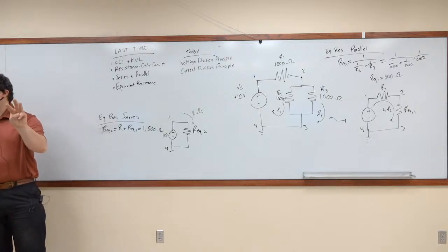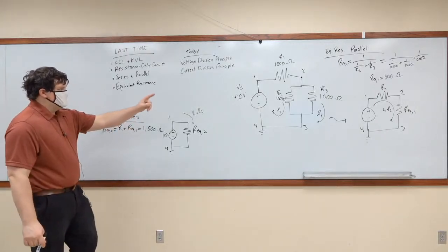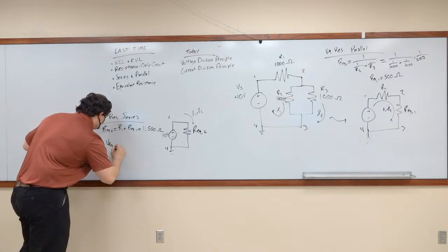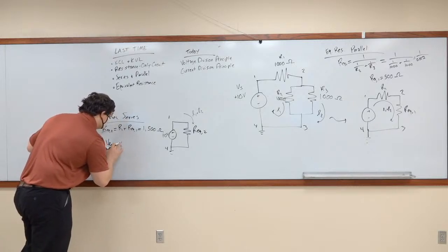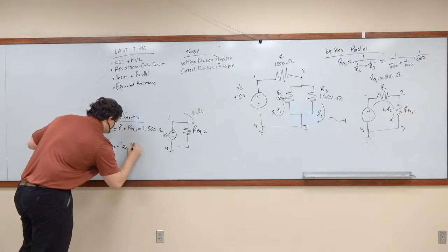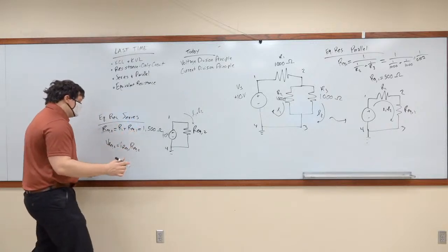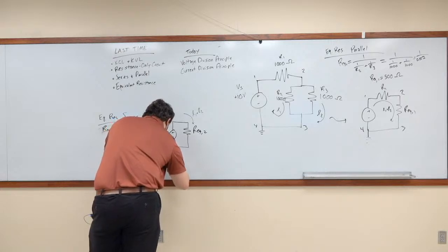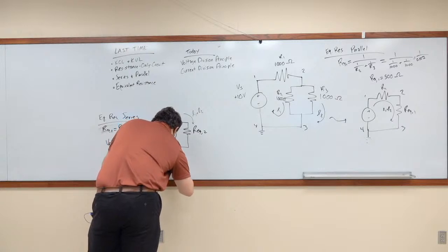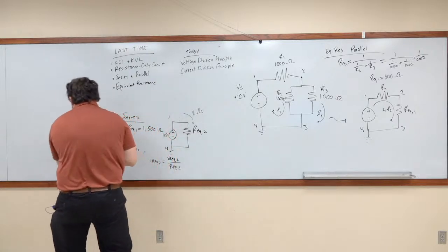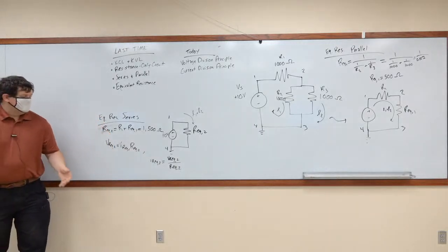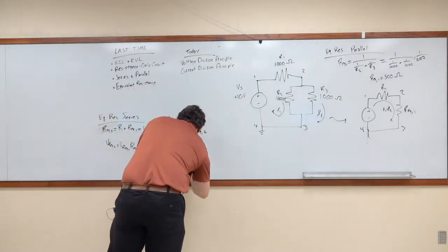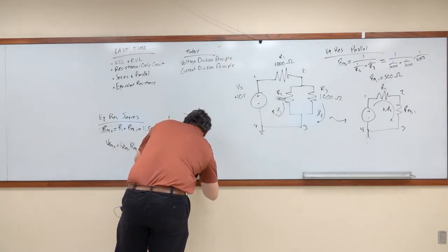You know 2 components, you can figure out the third. So we know it's 1,500 ohms, we know it's 10 volts. So according to Ohm's law, V REQ2 is equal to I REQ2 times REQ2. We rearrange this, and what you find is that I REQ2 is equal to V REQ2 divided by REQ2. It's just rearranging Ohm's law. Once you have this, V REQ2 is 10, REQ2 is 1,500. So 10 divided by 1,500.